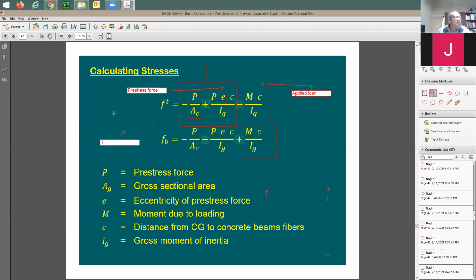This point, which is on the top, I'm going to call it point 2. Now, if you put this beam upside down, are you going to bring point 1 up because you called it the bottom? You're going to say no. Usually, you're going to have positive moment at the bottom, which means you're going to have tension at the bottom anyways. So if you put it upside down, the bottom point is always going to be positive and the top point is always going to be negative. You cannot change this fact.